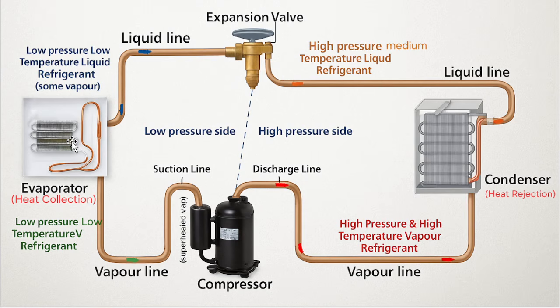Now let's imagine that you have put ice cream in the freezer at negative 25 degrees Celsius. And in your freezer or refrigerator, there is a refrigerant which boils at negative 20 degrees Celsius. Then it is not going to maintain that temperature of negative 25 degrees Celsius. This is the reason, okay? It has to boil at a very, very low temperature. So please keep this in mind.